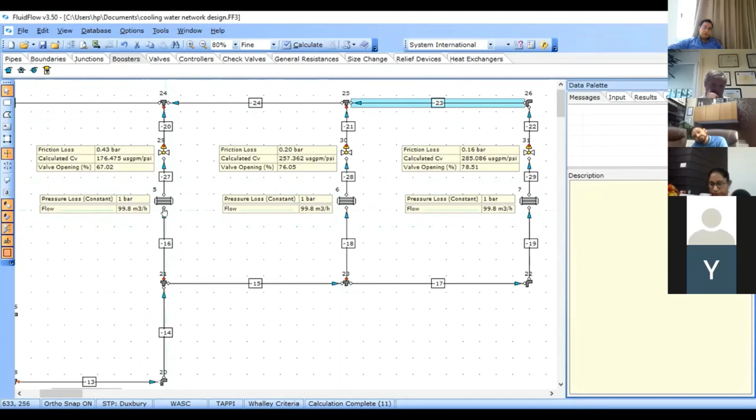So if the water is going in the shell side or the tube side, there is a chance that the shell side or tube side will not have full liquid. The tubes should be filled with this liquid or fluid, basically. Right? So there could be chances of overheating or some hotspot might get generated. Because of that, we'll always keep it on the downstream, so that even if there is throttling, that exchanger will always be filled with our liquid. That makes sense? Yes, sir.